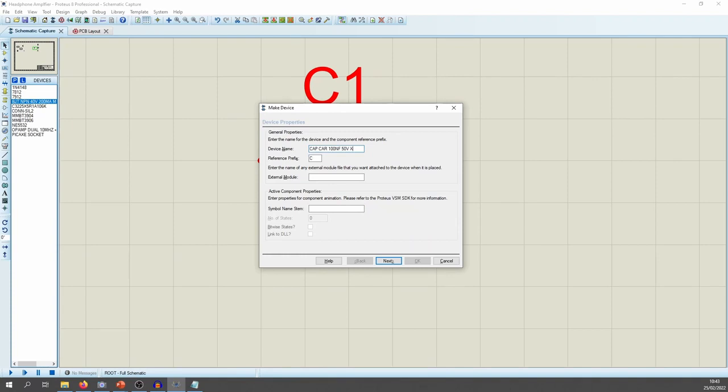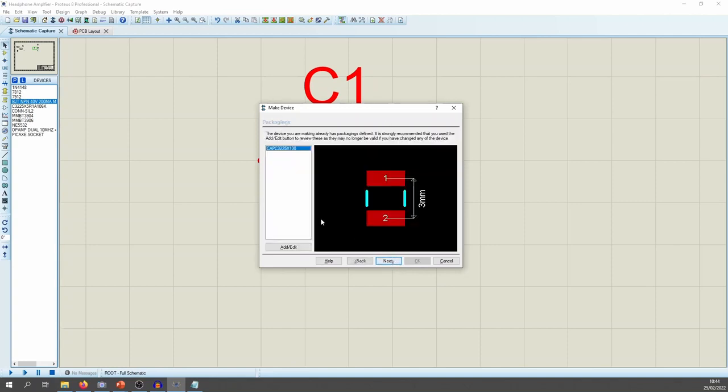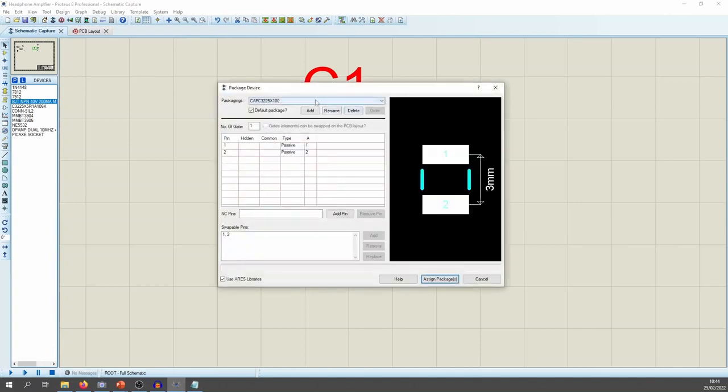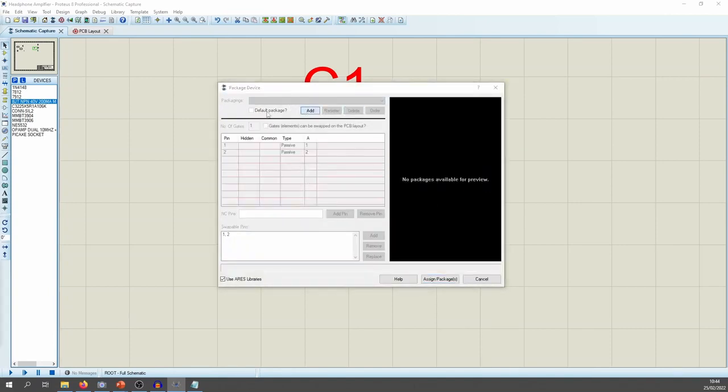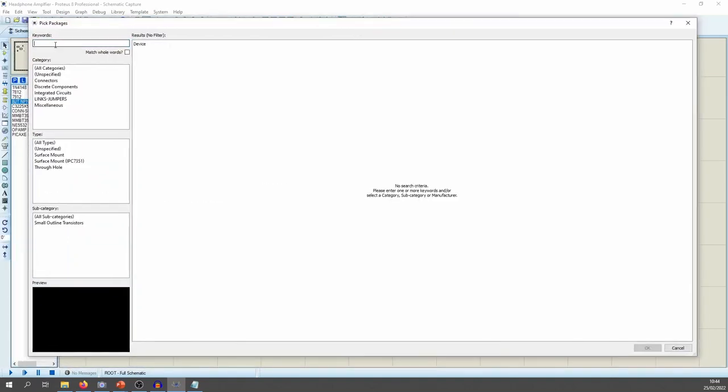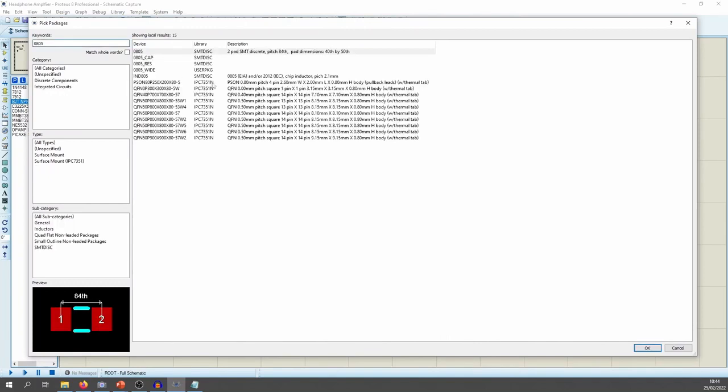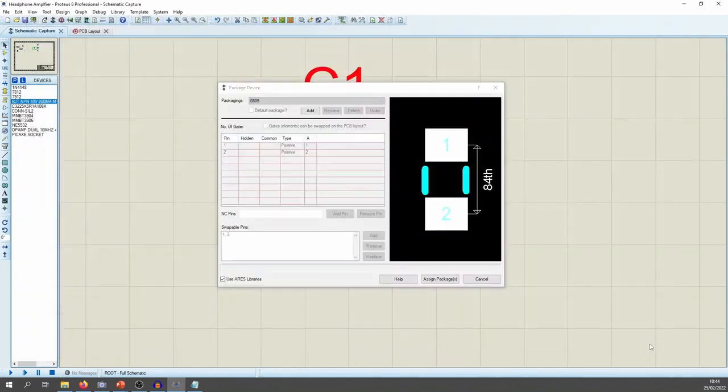And it's got a dielectric of X7R. That'll do. So you always put your capacitors' information in as capacitors. So it's a cap. It's the technology, the value, voltage, the dielectric. Then we're all good. Add edit. This is the easy part. Okay. I'm going to delete the existing package because that's just the one that came with whatever I chose randomly from the part picker. And I'm going to go 0805. There's a few different 0805 thingies here. There's 0805 cap and 0805 resistor. I've not been able to find any difference between these three footprints, so I just always choose just bog standard 0805. So 0805 done.